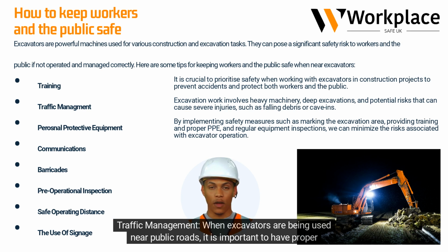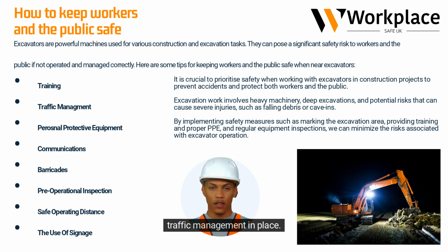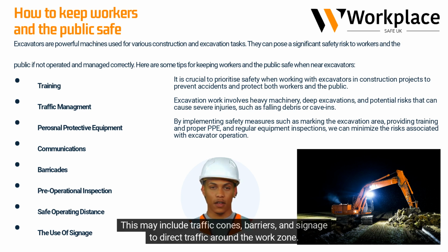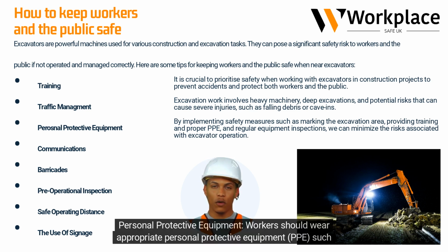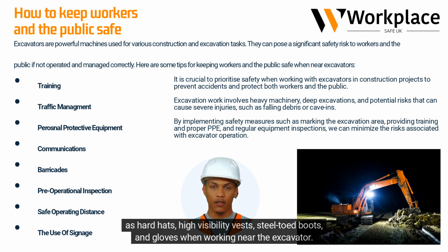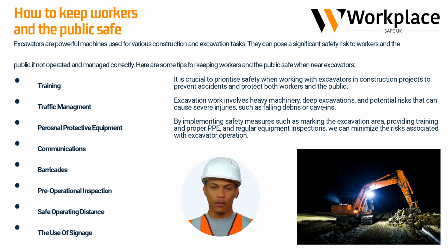Traffic management. When excavators are being used near public roads, it is important to have proper traffic management in place. This may include traffic cones, barriers, and signage to direct traffic around the work zone. Personal protective equipment. Workers should wear appropriate personal protective equipment, PPE, such as hard hats, high-visibility vests, steel-toed boots, and gloves when working near the excavator.